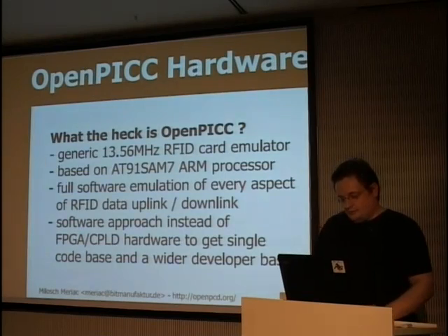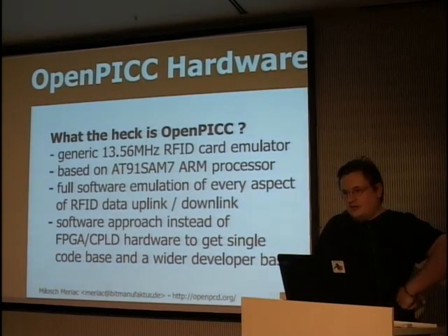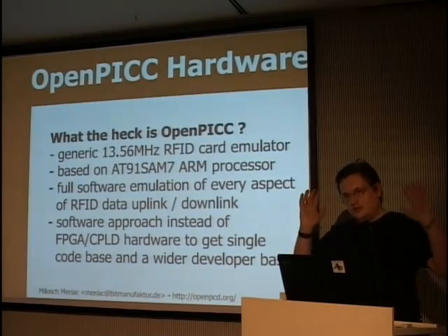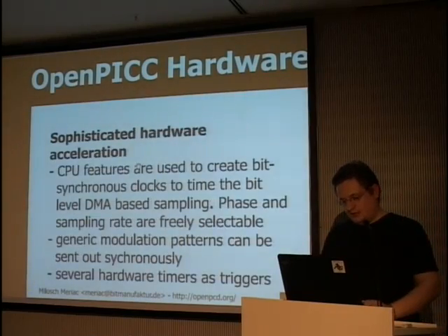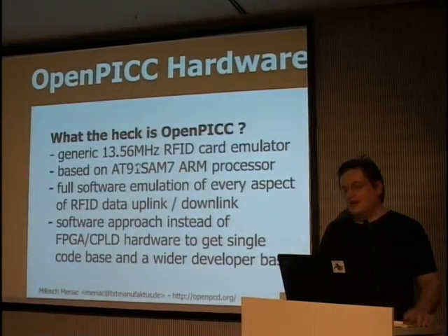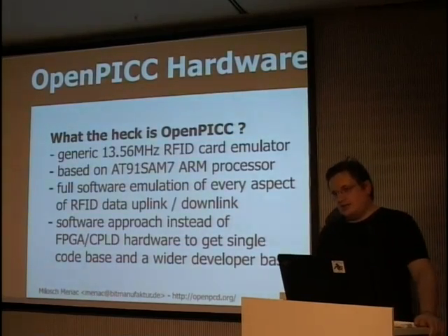So as I indicated, it's basically the very same hardware. The approaches are also very same. Again, this time we didn't take the 13.56 carrier clock from the oscillator, but we instead took it from the field, which required some smoothing and filtering. But basically, it's very same. We basically have the carrier.